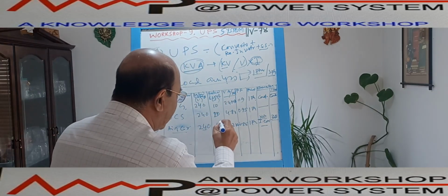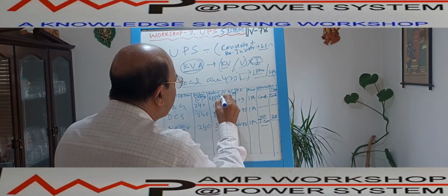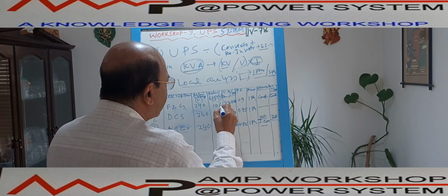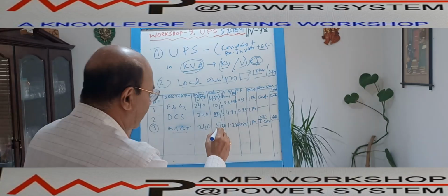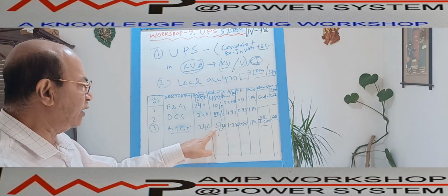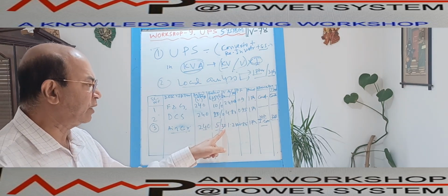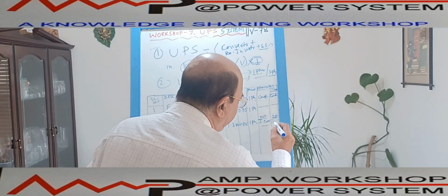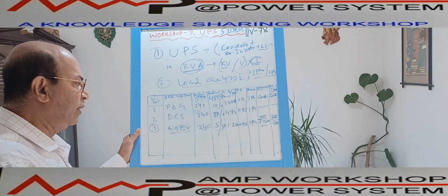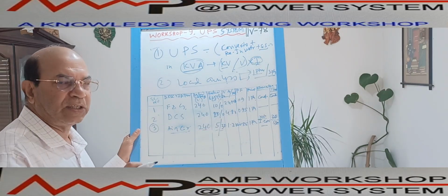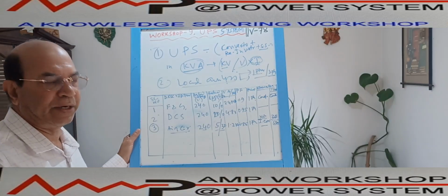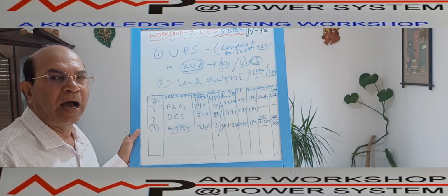So here we can write rated current and inrush current. For the earlier loads the inrush current is 0, there is no inrush current. But for this load, the air circulation system, I have an inrush current. Rated current is 5 ampere, but inrush current is 30 ampere. That may be required for 5 seconds, I can consider it that way. The current is 5 ampere continuous, but for about 5 seconds during the starting of this fan, it will draw 30 ampere. All these currents we are talking about are RMS currents.